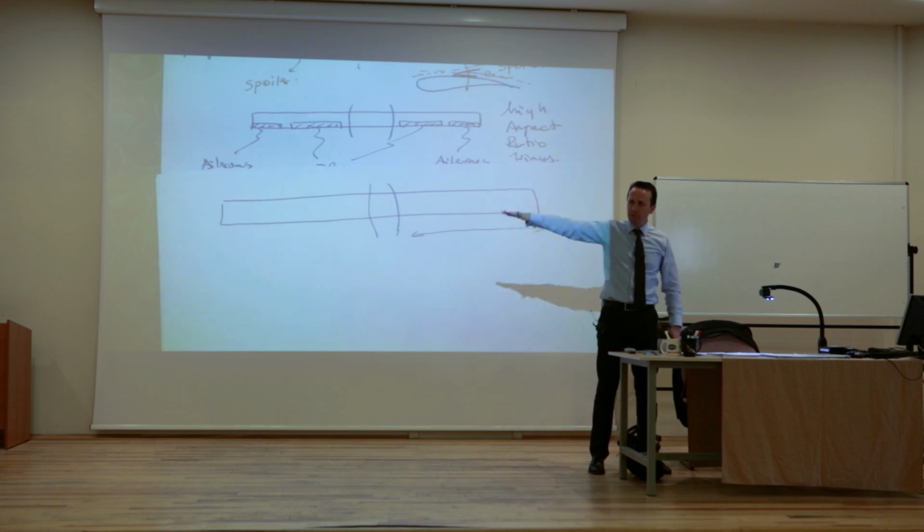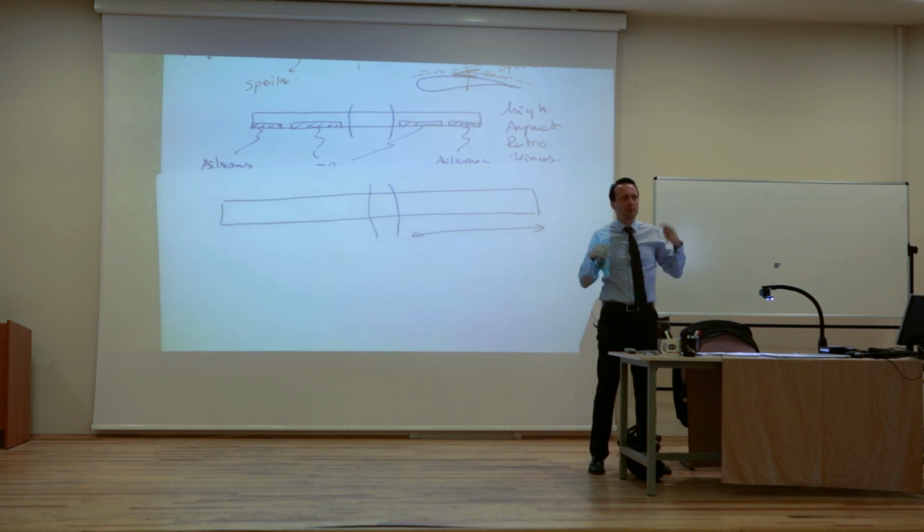So if the wing starts oscillating, you can take the aileron and go in the opposite direction and try to remove that oscillation. It's like noise-canceling headphones. Yeah? You measure the noise, and then you take the frequency and the amplitude and reverse it and give it as an input. It will cancel the noise, and you will not hear anything. It's very similar. You can cancel vibration with another vibration, with another oscillatory input. You have seen this in vibration, right?